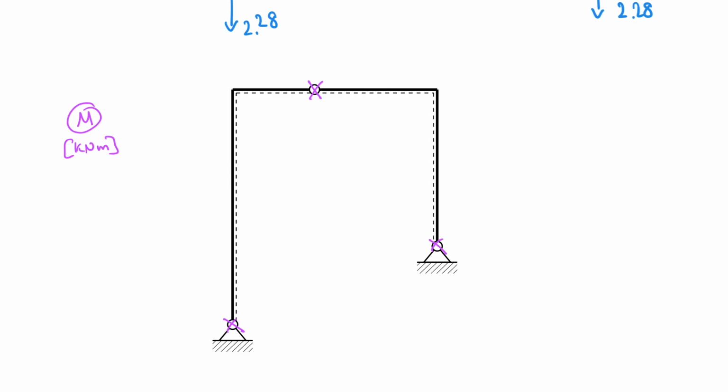We also know that I have a parabolic function here, x squared. I also have x squared there. And then I have it linear. So that would be x and x, but don't be fooled. Remember that there was a concentrated moment somewhere here. So there I must have a jump. And then last but not least, here I must have a function of x. And by the way, here also I have x. But I will erase this now just to not confuse myself.